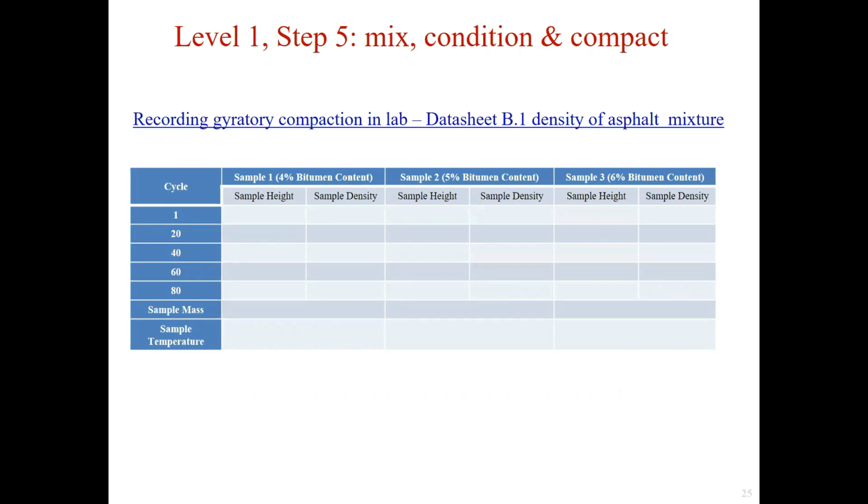This is the data sheet for gyratory compaction tests. This enables a selection of different compaction levels to match service conditions and simulation of long-term heavy traffic by compaction to refusal density. The refusal density is also the final density of the sample.